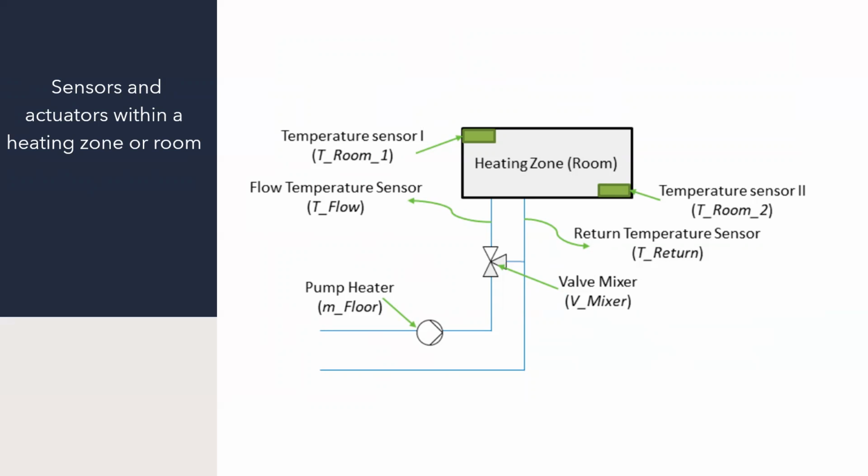In this test, the thermal storage corresponded to decoupling of the supply and distribution side. The calculation of the inner temperature is obtained by heating load calculation. The heating system in use in this case, underfloor heating, is simulated, and the heat loss and gain are taken into account.